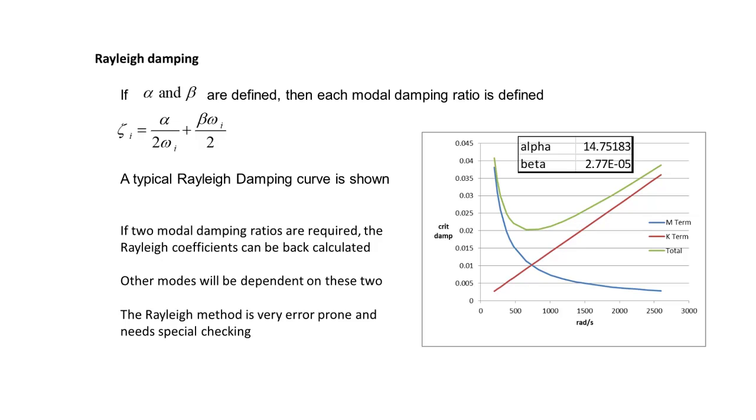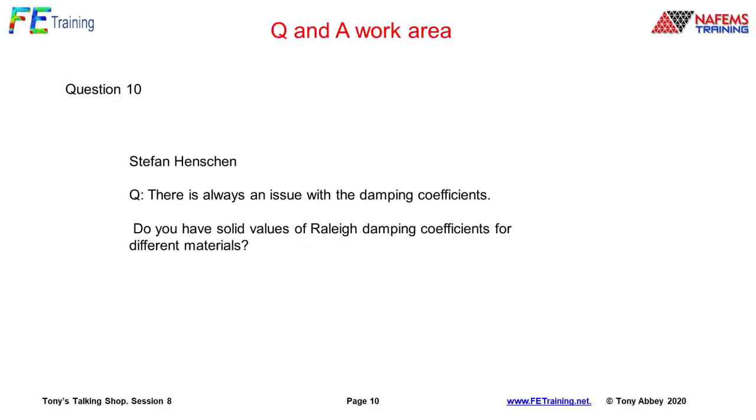Damping is dependent on materials to some extent, but it's also dependent on the structural form. For example, for fabrications, there might be higher damping levels than for an integrally machined component. So it is partially dependent on the material, but it's more dependent overall on the environment that the structure is sitting in. I generally talk about, on the course, damping levels running from very light damping, say 1%, 2% for something which is an integrally machined type of structure, all the way up to say maybe 10%